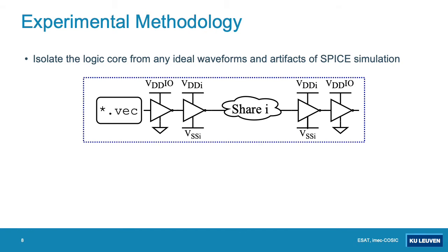We perform all of our experiments using the FineSim SPICE simulator from the Synopsys suite. As the circuits we use are very small, we need to prevent the impact of ideal waveforms and numerical artifacts of simulations, such that we can precisely isolate the core logic and observe the supply current of different shares independently. To do this, we buffer all the inputs, separating the ideal waveforms of, for instance, the digital vector file,